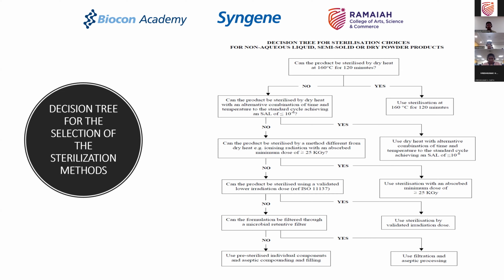And in such situations, your probability of failure on sterility assurance increases. Once a failure occurs on any sterility assurance, it leads to an investigation where you can't manufacture that product till you have investigated the root cause of why the sterility failed, and have put in mechanisms, techniques, procedures, necessary controls to make sure that this will not recur.